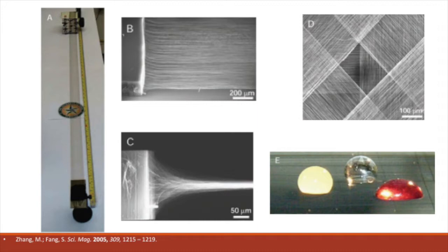Once these forests were purified, an adhesive strip was used to peel away strips of nanotubes oriented in sheets. Multiple sheets were then stacked on top of one another to form densified sheets, which displayed tensile strengths of up to 465 megapascals per gram per centimeter cubed. At the time, this was much stronger than the 160 megapascals per gram per centimeter cubed tensile strength of Mylar and Kapton films used for lightweight aircraft vehicles.